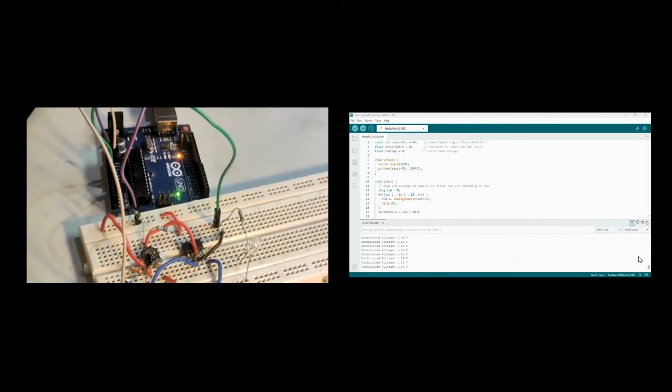Here in our lab now, I will just show you on this breadboard. I have made a circuit, that is your LM358 and Wheatstone bridge circuit. And this is my Arduino board, and the output connection, that is pin number 1, from here it is given to A0. This is the point A0, and the supply to run this circuit I have taken from 5 volt from here itself. So I will just give you a demo.